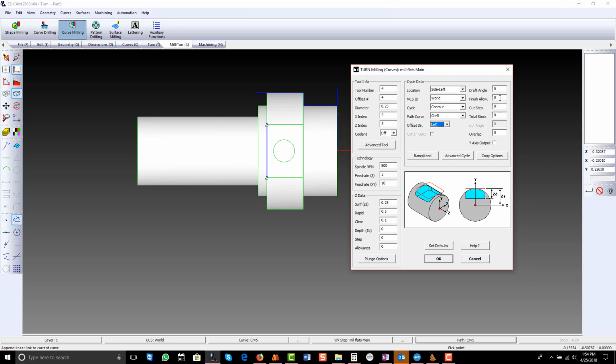The finish allowance, let's give it a negative finish allowance, 0.03, so that I get an overlap of the tool instead of being tangent to the edge. If you're using a y-axis, it's as simple as just putting a check in the checkbox. That's pretty much it when you're working with a y-axis. EasyCam takes care of the rest.